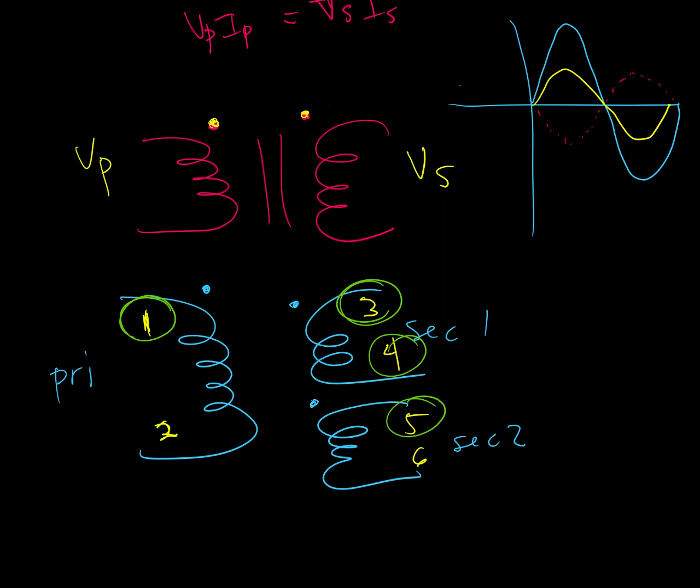So if you're looking between the two leads of the primary, you should get a small ohmmeter reading. But if you're looking between the primary and the secondary, or two different secondaries, you should get the open circuit reading. Okay, if you get 0 or a small resistance in that case, then you know that something's wrong.